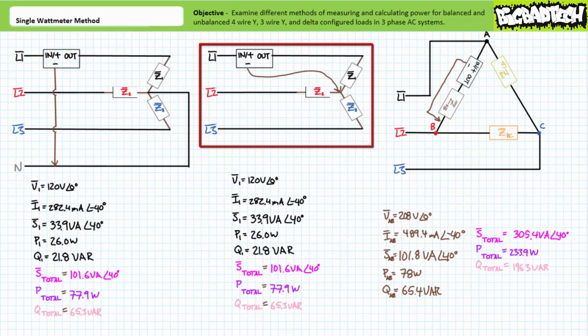What if this central node internal to the 3-wire Y configuration was inaccessible? Oftentimes it isn't accessible, the classic example being a 3-phase AC Y-configured motor where 3 ends of the Y configuration of balanced windings are externally accessible, however the central node is locked up tight. Directly measuring current external to a balanced 3-wire Y configuration is not a problem.